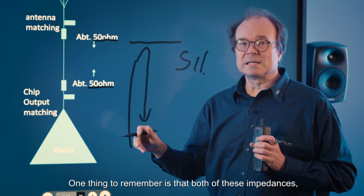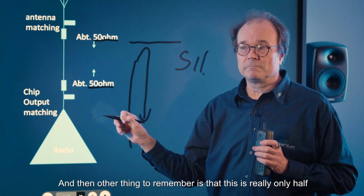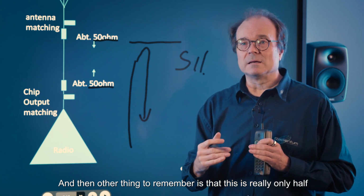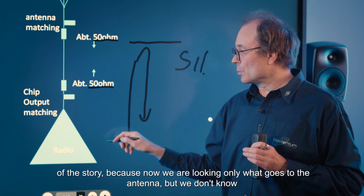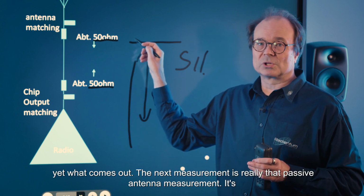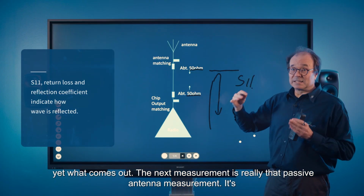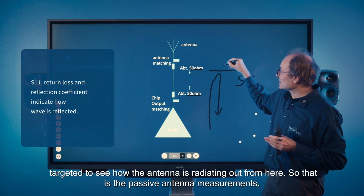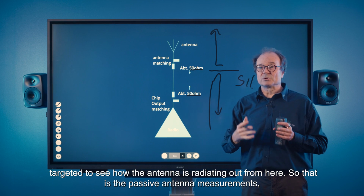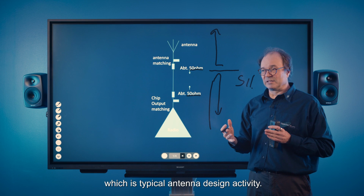One thing to remember is that both of these impedances are frequency dependent. The other thing to remember is that this is really only half of the story, because now we are looking only at what goes to the antenna, but we don't know yet what comes out. The next measurement is the passive antenna measurement. It's targeted to see how the antenna is radiating out. That is the passive antenna measurement, which is a typical antenna design activity.